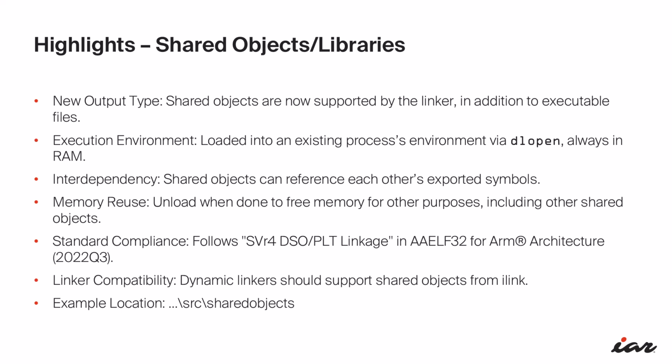We have added shared objects libraries. This is basically the same mechanism as you are used to on the desktop. If you are in a Windows desktop environment, you have DLLs. If you are running Linux, you have the .so files, the shared objects. And this is an implementation that is very close to the Linux shared objects implementation. So the linker can now generate not only a pre-built ELF file, it can also generate a shared object as output.